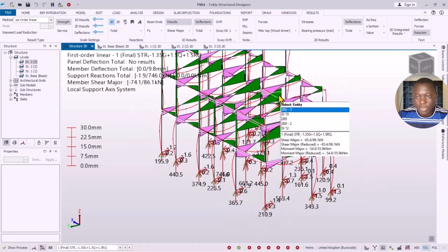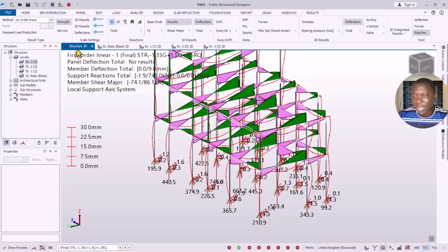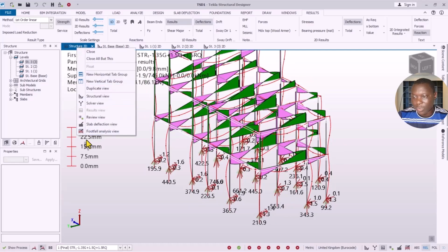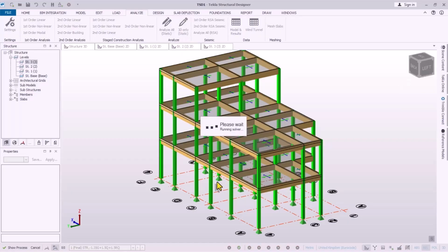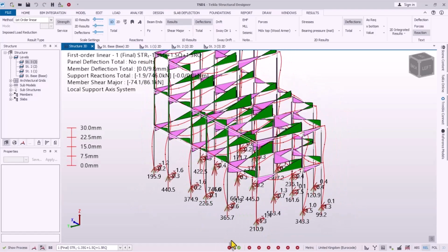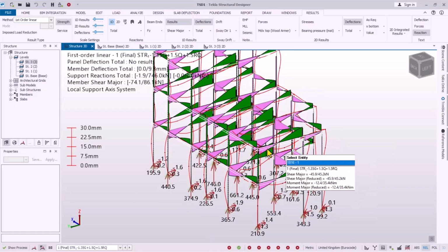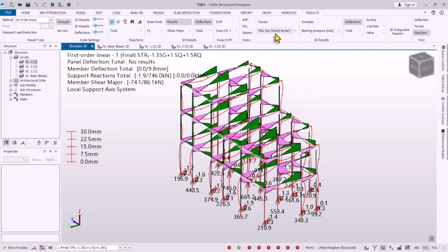Okay, so these are the things we need to check for now. So we are at 3D. You can also right click on this and then you come to this provisions, change it to the structural view. We'll have this. Okay, so analysis is done. I want to run this 3D only static. I click on that. So that will also run successfully, and then we see the result as well. It's very, very important. Okay, so having done all of this analysis, we don't have anything much to check right here. This provision is for design. All right, some of this provision is for design.